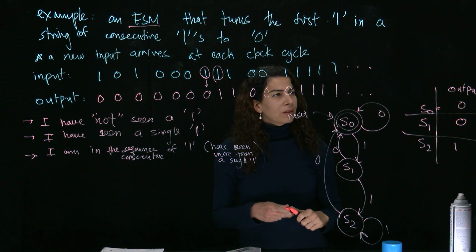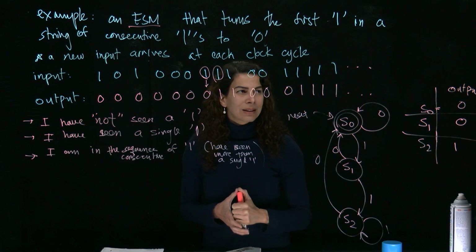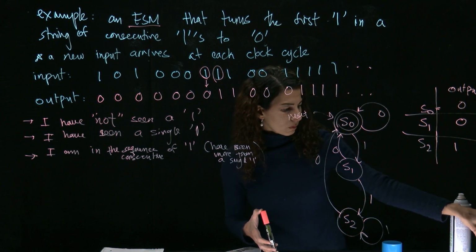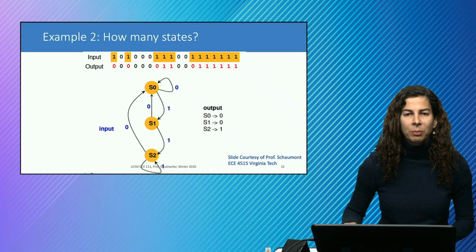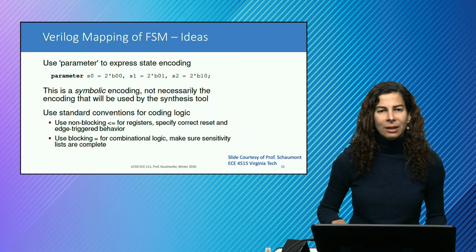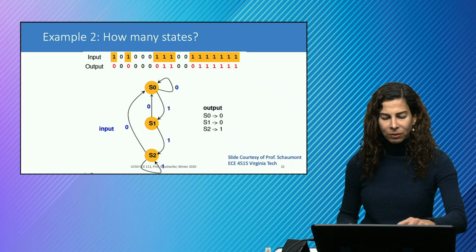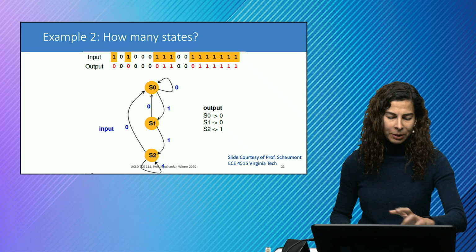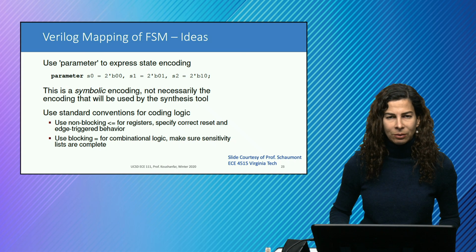So now that we've designed the finite state machine, let's see how this thing looks in SystemVerilog. Here I have on the slide the same thing I just drew on the board. What we will see here is that, if we have these 3 states, we could use parameters, and because it's 3 again, we can use 2 bits to define 3.